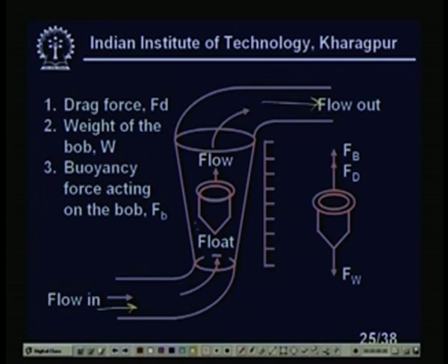You see this taper is so small that it is very difficult to see. The size of most rotameters is usually like this pen. It is not very huge in size. The taper angle slowly increases. At the bottom it is a smaller included angle, and it is slowly increasing in this direction. But the tapering is so small that it is very difficult to visualize with the naked eye, because the rotameter is made of hard glass.